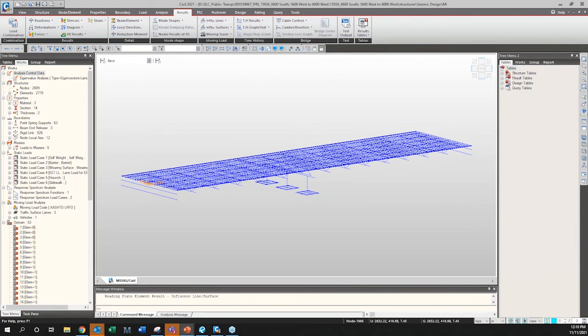Your boundary conditions directly introduce or remove stiffness from your system, and oftentimes this can have drastic effects and impacts on how your model behaves. So it's critical that you establish the correct stiffnesses so that your loads will go where you expect them to go within your structure, and this will ultimately inform design decisions, because you're going to size members and establish design parameters, criteria off of how that load moves through your structure. So it's extremely important that we get it right.